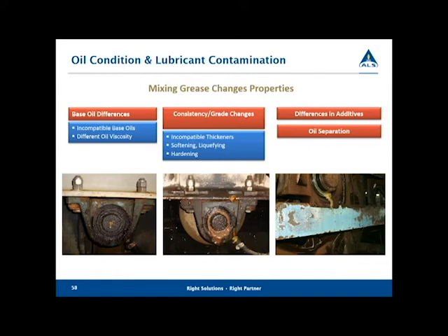And just go forward, regardless of what people say about whether thickeners are compatible or not, just assume they're not, because unless you put this through some serious, expensive testing, you're not going to be able to really figure out if these thickeners are compatible or not. They can either soften and liquefy and pour out, or they can actually harden in certain cases. It's not very common, but it does happen.